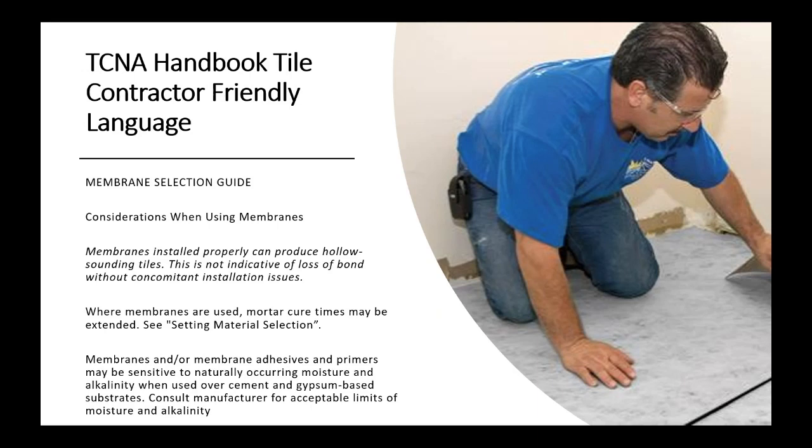Also, when membranes are used, mortar times can take a little bit longer to cure, especially in cold weather, of course. But because you're working on a waterproof membrane, or could be, again, recycled rubber or a bitumen membrane like pictured, it's not the same absorption as what it is to a concrete slab. So, of course, it's going to take longer for that mortar to start to set.